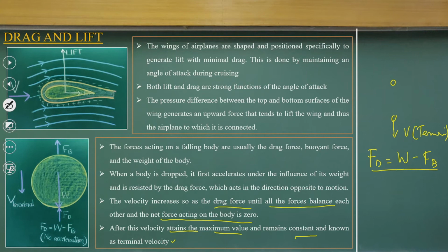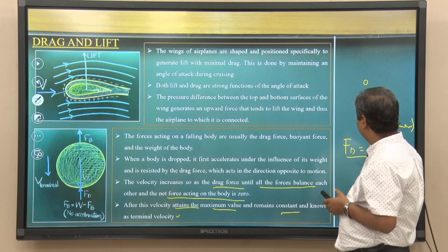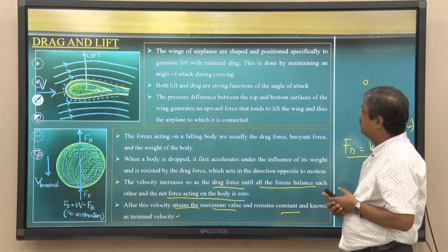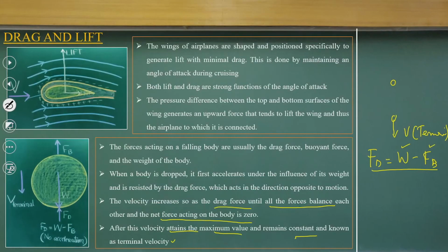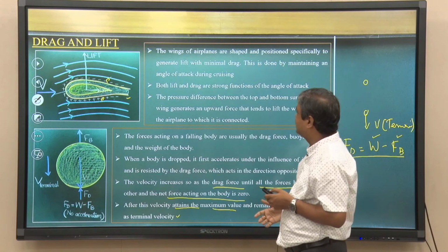What will be the weight, what will be the buoyancy force, depends on the fluid density and the density of the dust particles. So, we can always compute what will be the weight, what will be the buoyancy force, and you can compute the drag force. There could be flow separation and all, it also depends on the Reynolds number and the roughness. The same way, when you flow past aerofoils, you will have positive pressures, there will be a negative pressure difference, and there will be friction drag as well as the form drag, or drag due to the pressure difference.